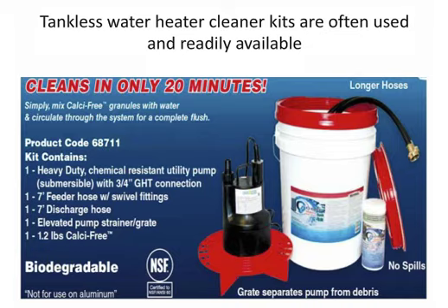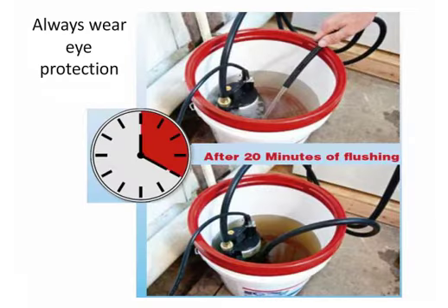So not badly priced, and it's all compact. You can see here that you're supplying that cleaning solution through, in this case, a tankless, but I'm telling you, you can use this product to go through the heat exchanger or the heat pump. Returning it back, you can see at the bottom the discoloration after about 20 minutes of flushing. So guys, don't race through it. Make sure you give it the due time it needs. And by the way, always wear eye protection.